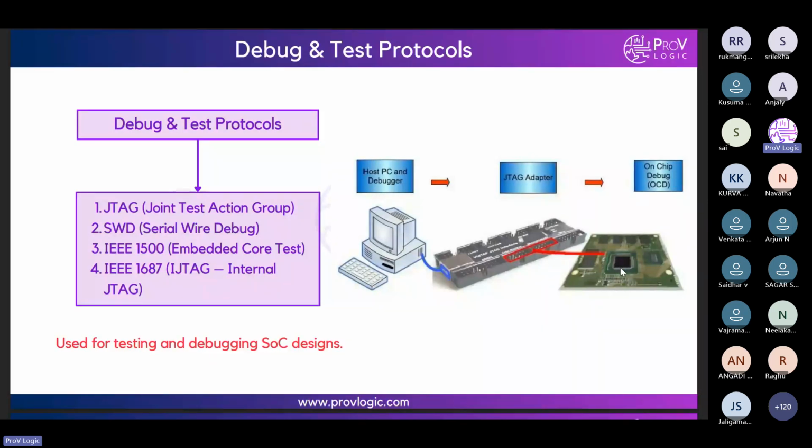From every team, every block, we gather the information of all the test cases, and there again we do the functional verification, whether every test is verifying properly or not, whether it is getting 100% coverage or not. Everything we check, even after the manufacturing process is completed. Another thing, if you see here, there is a JTAG adapter in the middle. That means this is an FPGA, which is used to take the information of the SOC by using the JTAG connector.